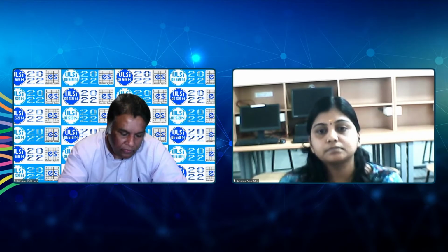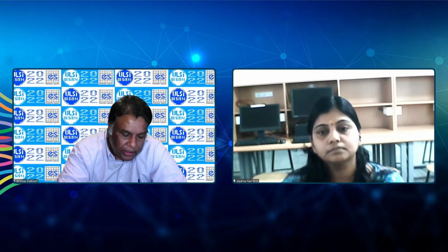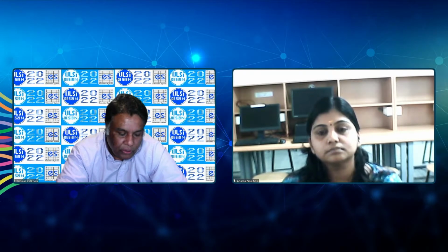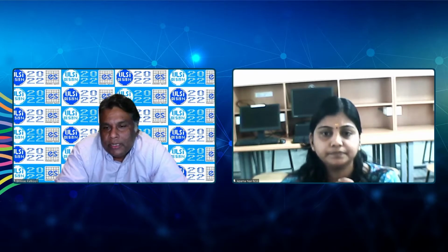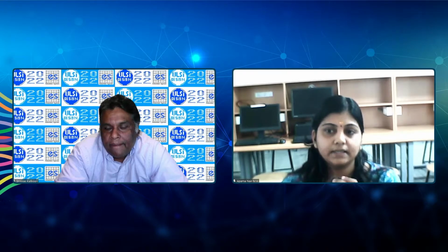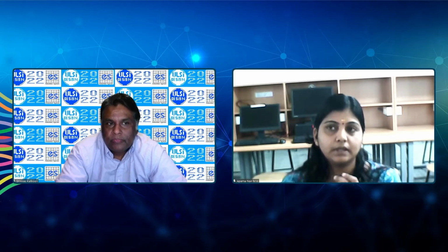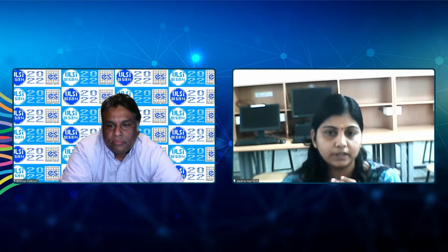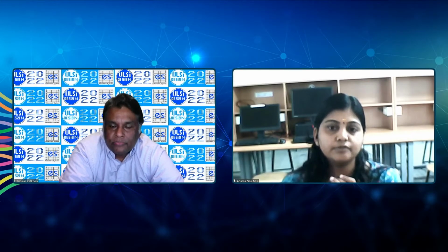I have one question. You said you replaced the registers with an asynchronous FIFO, right? Yes. How did you determine how big the FIFO should be? Initially we fixed it to a depth of 8. Since in the existing literature the size of the register banks depends upon the payload size, we took 2 different payload sizes, but we kept our FIFO depth at 8 only, and we worked with different payload sizes.